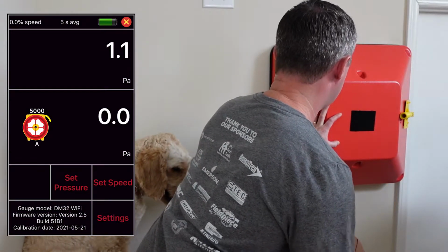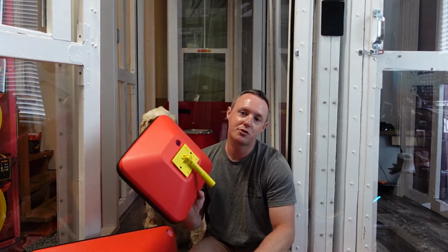There's not really a particular number here that we're looking for. We're just looking for some leakage that might be higher than other areas of a similar penetration in the house. For example, if we go around measuring can lights or receptacles and we're getting maybe 2 pascals of pressure, and then we test another one and we're getting maybe 10 or 12, then that's a good indicator that somewhere in that wall assembly, it's connected to the outdoors a little more than other assemblies like it.